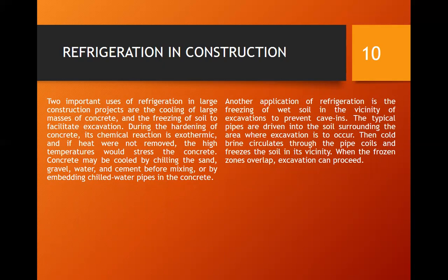Another application of refrigeration is the freezing of wet soil in the vicinity of excavation to prevent cave-ins. Typically, pipes are driven into the soil surrounding the area where excavation is to occur. Then cold brine circulates through the pipe coils and freezes the soil in its vicinity. When the frozen zones overlap, excavation can proceed.